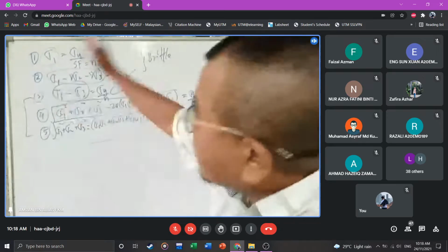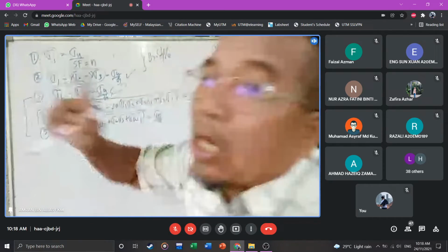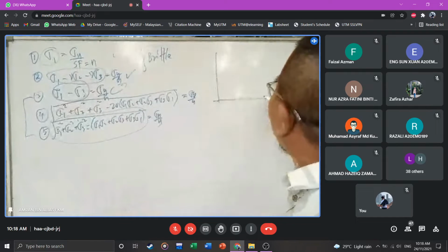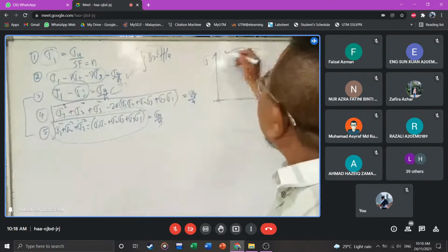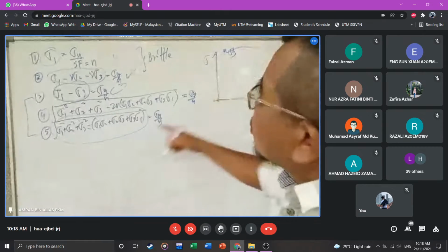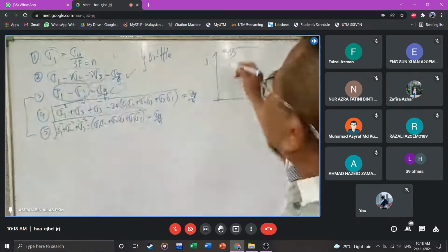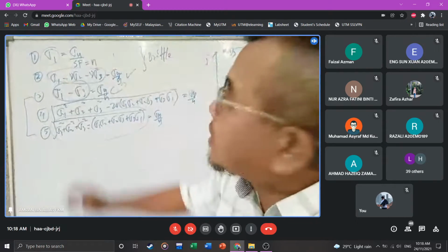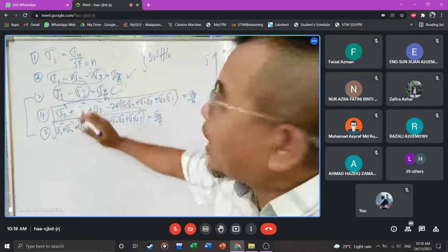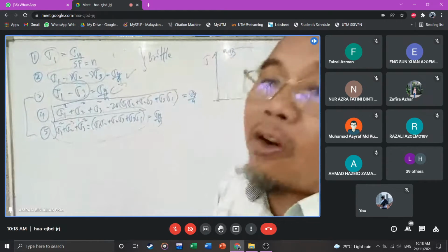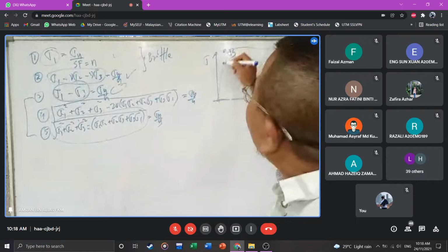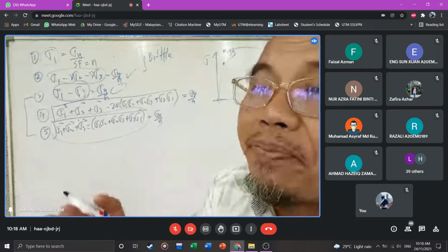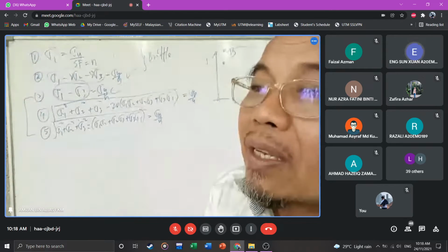Yeah, those are basic functions. This is one value only. This is several values. Whatever it is, this is easy for you to understand. And when the limit is there, that is sigma y. So whatever stress that we calculate here, whether Rankine stress, Saint Venant stress, Tresca stress, Hencky stress, or von Mises stress, the stress must be less than sigma y for it to be safe. Clear now? Clear. Okay, now